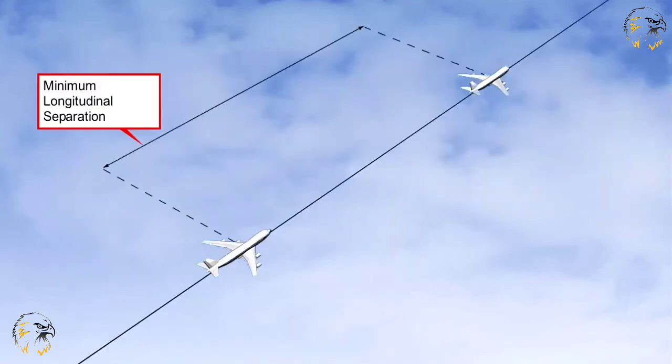Longitudinal separation is more complex to apply. In procedural air traffic control, not radar control, the position of the aircraft is accepted as the position that the pilot reports. This is obviously as accurate as the pilot and the navigational equipment he is using is able to be. Positions are usually reported as geographic positions, supported by navigational aids or specified radio navigational fixes.